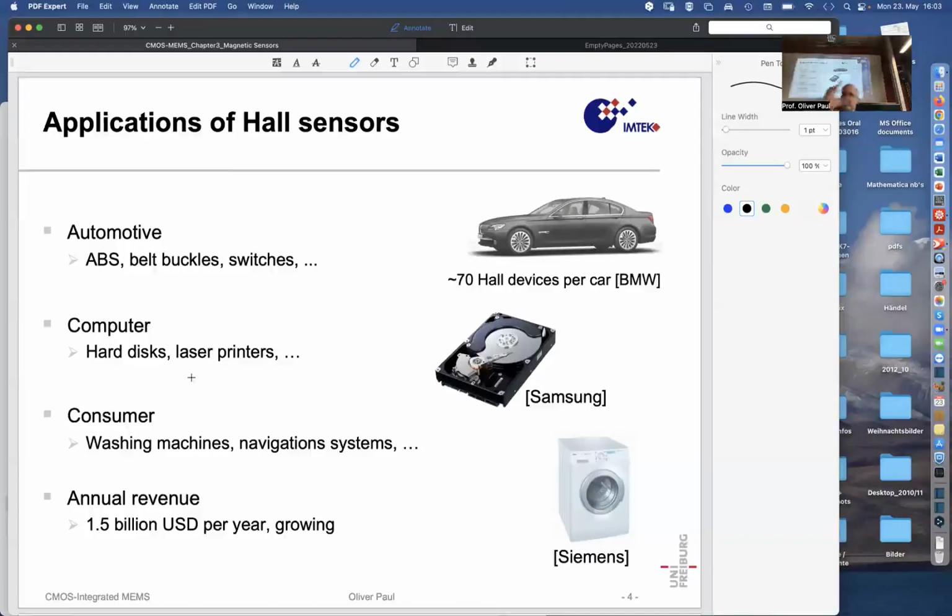Then also the position of the motor, to time the spark for ignition of the fuel in combustion engines, is of importance, because Hall sensors allow measuring the rotary position of the motor by some magnetizable dented wheel with a magnet close by and a Hall sensor nearby that measures the number of these spikes or indicators, regularly placed, that pass by to determine the exact position, so that ignition can occur not too early, which would be counterproductive and let the motor stall, or not too late, when it's already too late to do a full combustion.